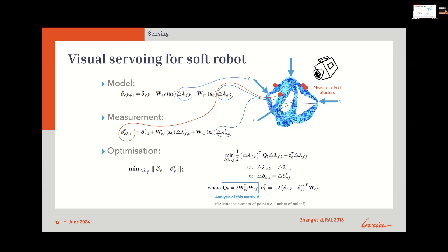And so here, the basic idea is that we will create new constraints, not only actuator constraints, but we will put some constraints on some points where we are able to measure the real position on the robot. So we will put some marker points on the robot, and we will measure the difference between the real marker point position and the marker point in the simulation.